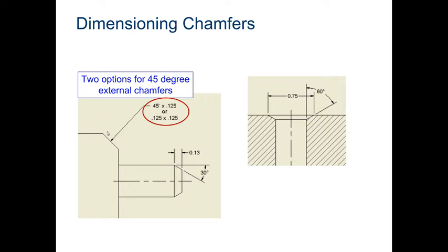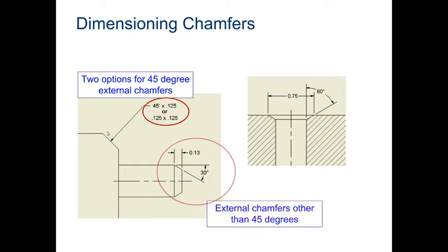There are multiple chamfers. There's an external chamfer, which is basically just the outside of a part. There's an external chamfer inside of a part, which kind of freaks a lot of people out. But basically, this is the end of a bolt. This part shows the end of a bolt, and the reason they have them is so that you can easily align into a hole. Now, if you have a bolt that's really tiny, and you're trying to put it in a tinier hole, it's really hard to align them. It's really hard to make them fit. So they use these chamfers to basically auto-drop those pieces in. They're easier to get into.